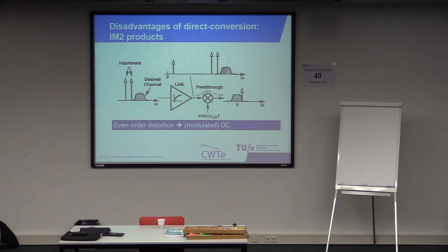Because even though the sign at the input has changed for this and that one, since I have a squared function, the distortions both become positive, right? If the input signal here is 1 volt, I get squared, it's 1 volt. Here it becomes -1 volt, but squared is 1 volt. I subtract them, the second order distortion disappears.